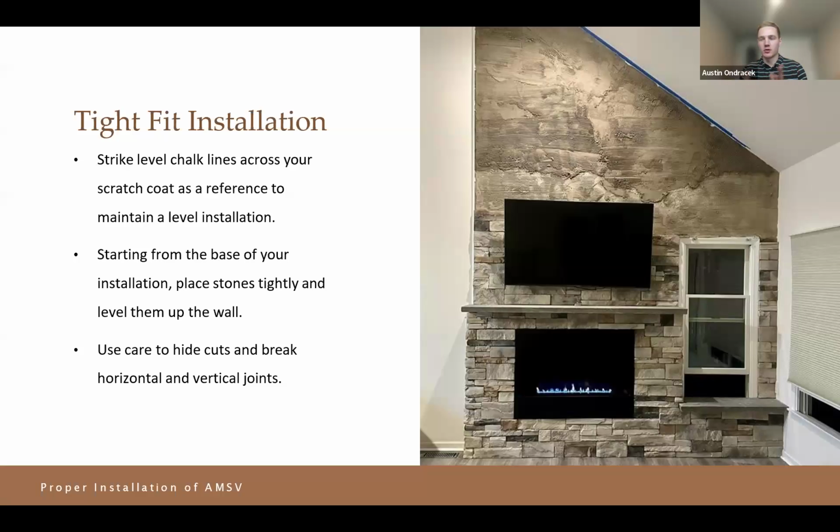Tight fit. Depending on how you need it, strike level chalk lines. This is a best practice for really any hardscape or, in this case, manufactured stone installation. That just helps make sure your project is not going to have some weird wonkiness to it once it's installed and it has the look and the feel and transition that you wanted after it's installed.